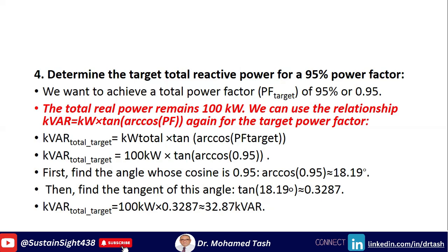Then we will find the tangent of this angle, which is 0.3287. And in this case, the kVAR total target will be 100, the total real power, multiplied by 0.3287, and it will give us 32.87 kVAR.